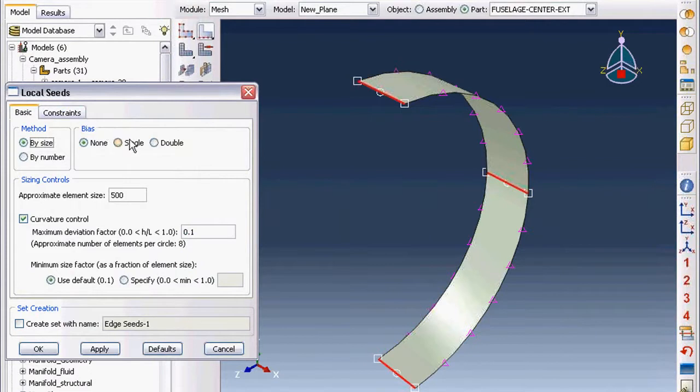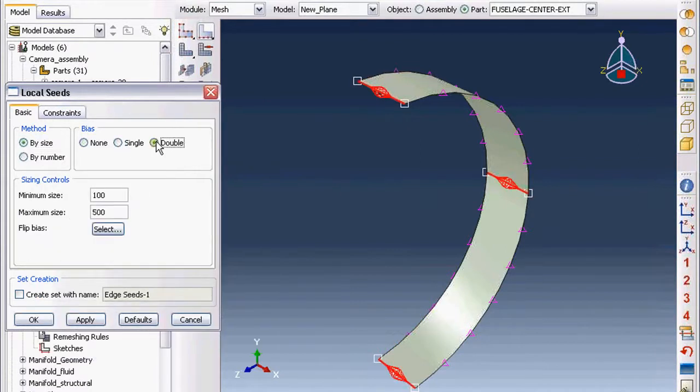This dialog box here controls the meshing behavior by defining the mesh bias either by size or by number. There are also, of course, options to renumber the nodes in your mesh plane along a certain edge, or apply a global renumbering scheme to all your nodes.